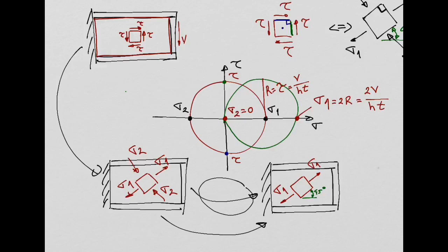Okay, so this is the Spar. It's an important thing in aircraft structural design. Basically, we allow the web of the spar to buckle, but it's a controlled buckling, if you want to call it that way.